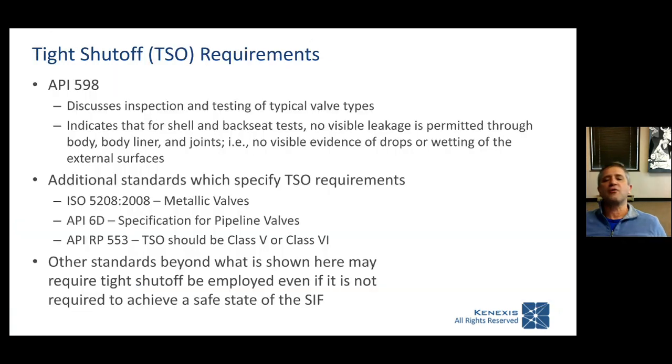But before we do, I'm a dog with a bone here. I'm not going to let go of that tight shutoff thing, because of so many bad SRSs I've seen, and I have seen a lot of really bad SRSs. Having just a TSO designation is something that you prefer not to see.